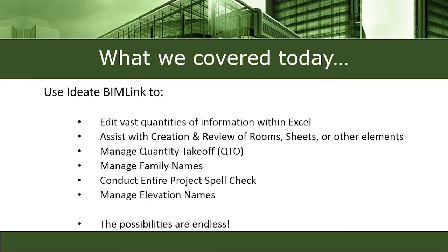So what we covered today is we used Ideate BIMLink to edit vast quantities of information. So you think about, again, changing the room names from lowercase to uppercase, or being able to assign the correct view template to 500 views. That would be very difficult doing it manually within Revit. But with Ideate BIMLink, you can do it in a matter of seconds.